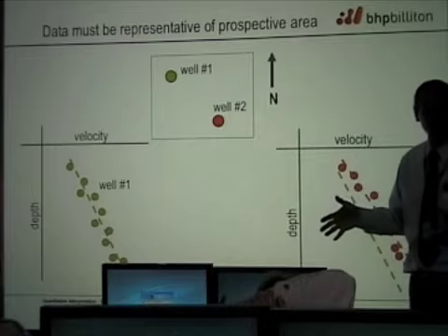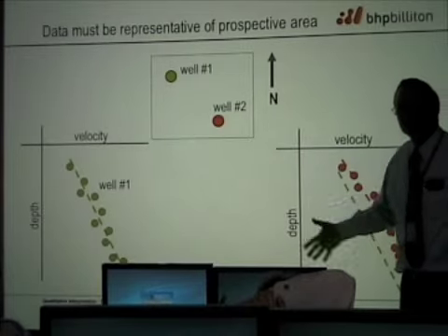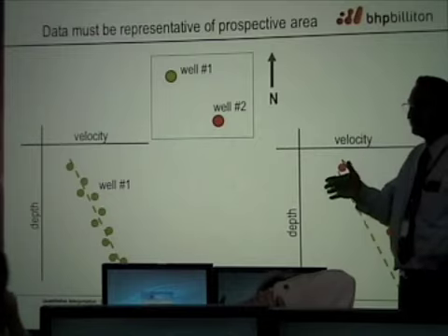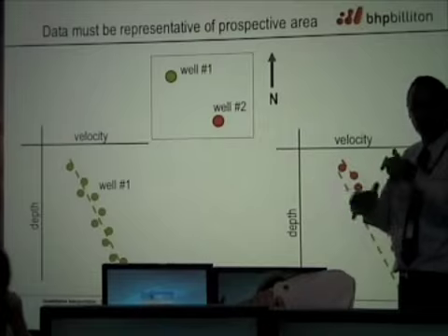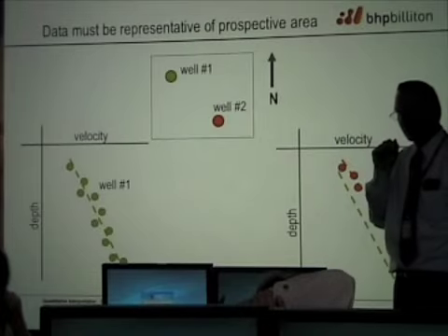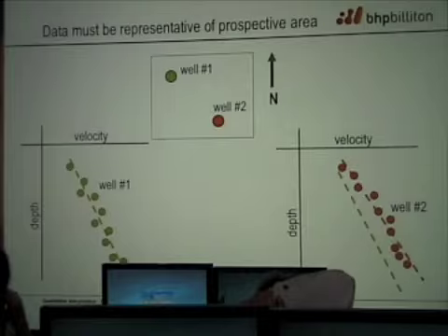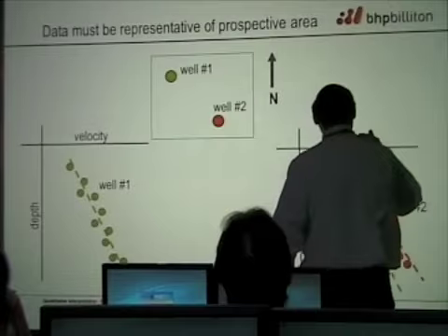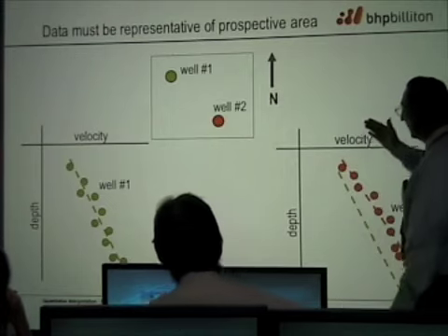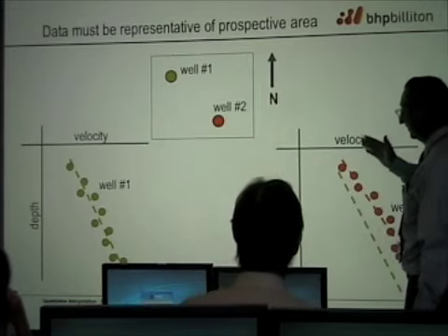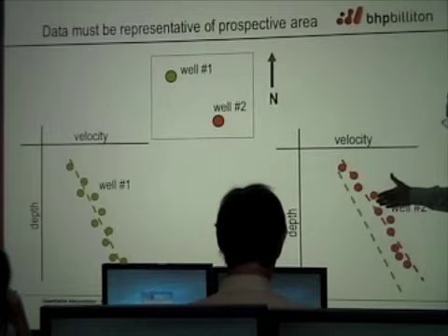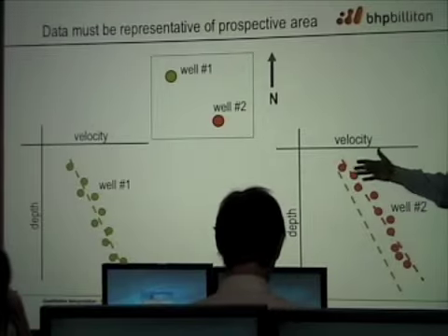But I only have 6 wells, and there's a big 300 square miles or something, and so I gotta know, I really hope that they all have similar properties, so I don't have to go fooling around with geographic variation properties. Well, there's two wells, so I get a velocity versus depth in well 1 and a velocity versus depth in well 2. One procedure I think you should always follow is to fit your wells separately and then compare well to well for whatever variable you're trending against.